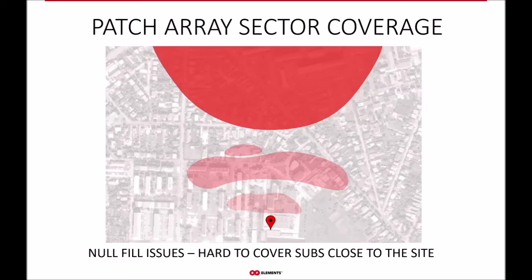As illustrated here, this is how the coverage looks in the case of a high gain patch array antenna. The area near the tower is covered by the side lobes, if at all. And these side lobes change with frequency, meaning you can't really provide stable coverage to the customers near the tower. Now, this zone of uncertain coverage increases with the gain of the patch arrays. So as we keep increasing the gain of these antennas, these issues get worse and worse.